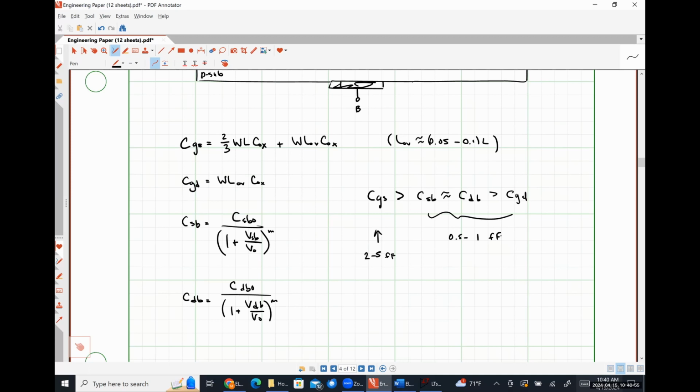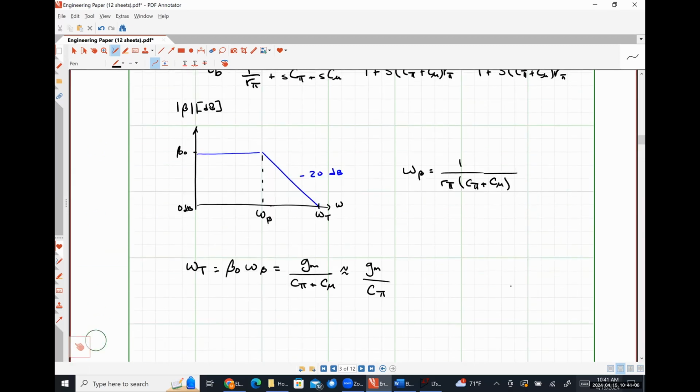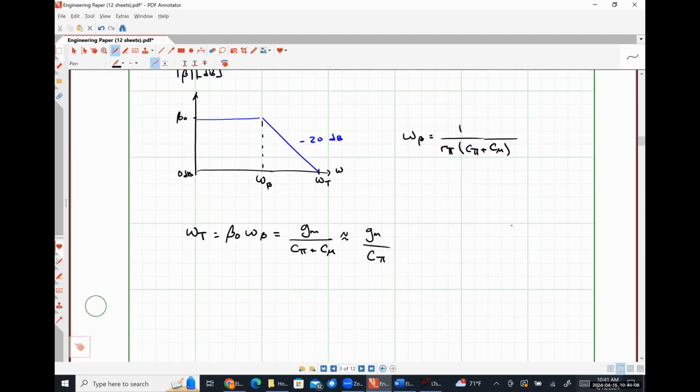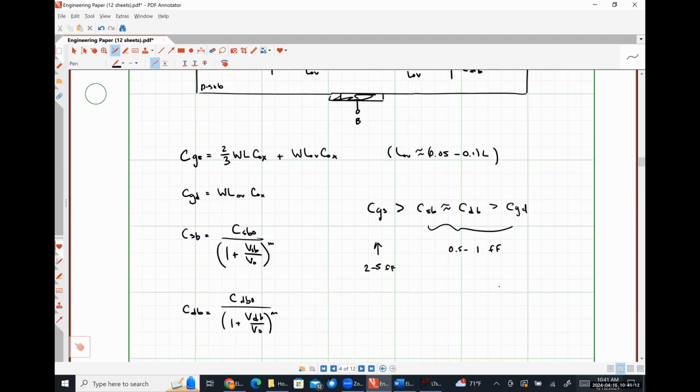So the capacitances for the MOSFETs, how do they compare to the capacitances that we talked about for our BJTs? Smaller, a lot smaller, about an order of magnitude smaller, I believe, right? So MOSFETs typically don't hit the high frequency regime until later than BJT-based devices because the internal capacitances are smaller.